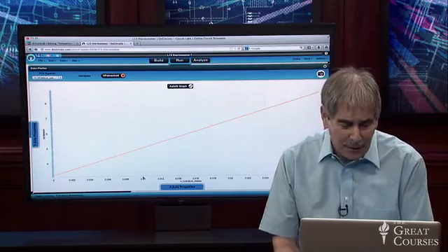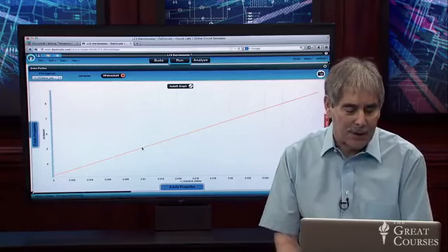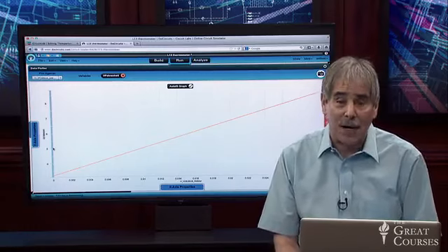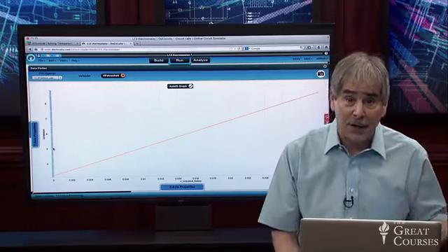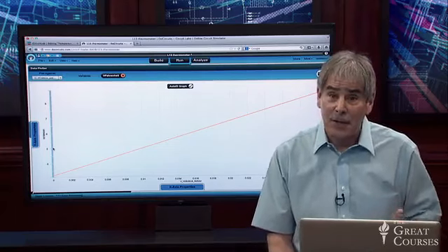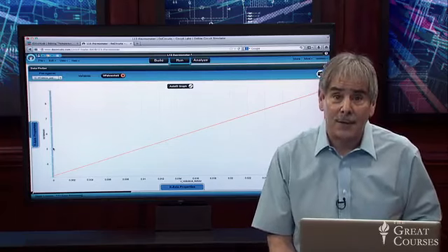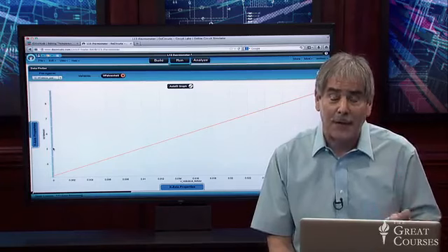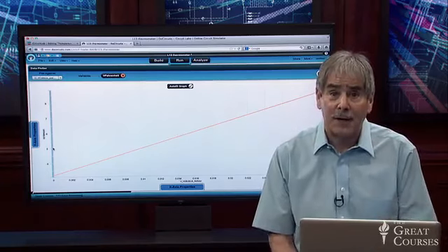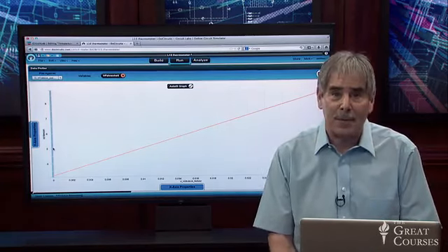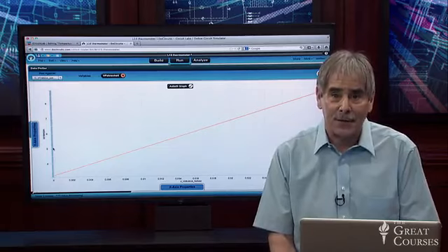For example, 0.01 volts, 10 millivolts, corresponds to 5 volts at the output, so 10 degrees Celsius corresponds to 50 degrees Fahrenheit. That was a pretty sophisticated assignment. To work that out and get the summing amplifier to sum in the 32-degree offset, not trivial. If you did that, pat yourself on the back for doing a really sophisticated circuit.